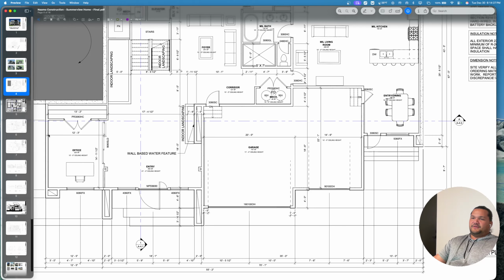This office, from the inside of this wall to the outside of this window, should be a certain length for this window or this glass door case here. That's what you need to verify with the client. When you're doing the estimating portion, you have to make sure every single thing is essentially itemized in this project.